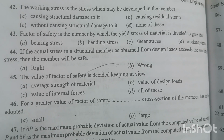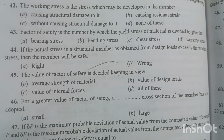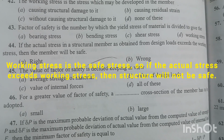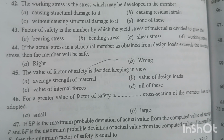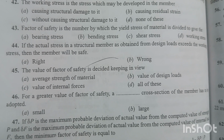Question number 44. If the actual stress in a structural member as obtained from design loads exceeds the working stress, then the member will be safe. No, if the stress exceeds the working stress, that means it's greater than the permissible stress, then the structure or member will not be safe. So option B is the right answer.